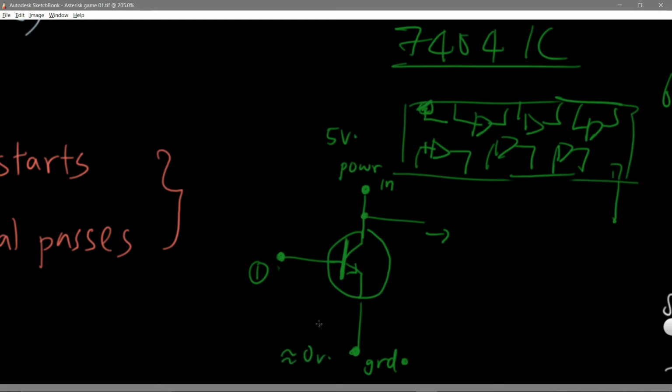So the potential difference is very great, and there is almost no resistance. So the majority of the current and voltage is going here, and this output will be interpreted as logical 0 because it's on low voltage and low current. So this is how a BJT inverter, a BJT NOT gate, works.